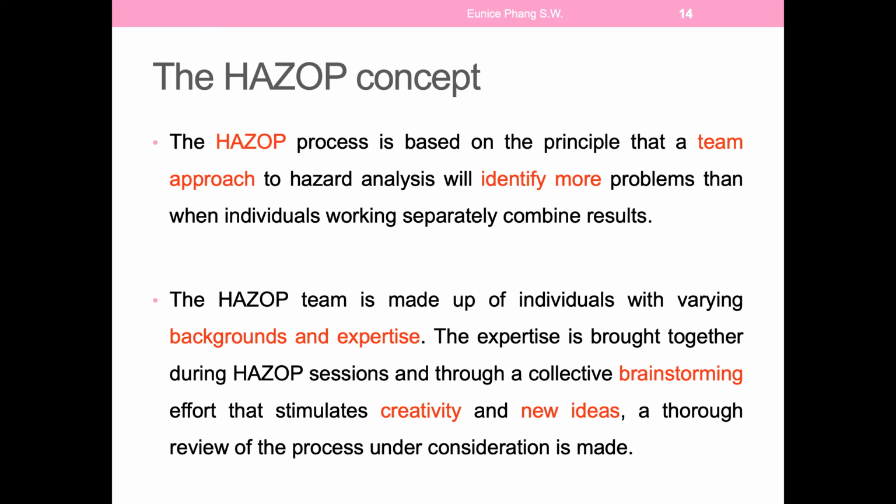If you want to do a comprehensive HAZOP analysis, it always needs to be done in teams, and you want teams of diverse backgrounds, meaning you do not want them just from engineering itself. You want some of them from production, some from production planning, some from the QC, quality control departments, so that you look at different levels of what could go wrong and how you want to prevent it.